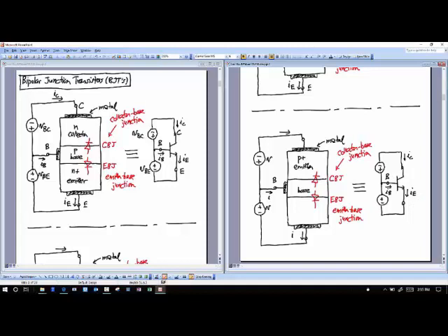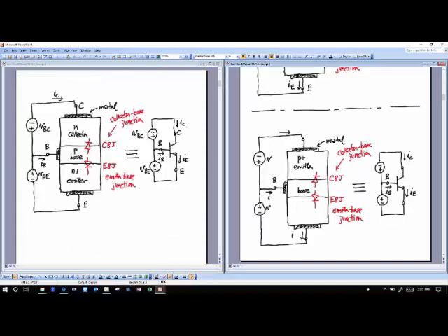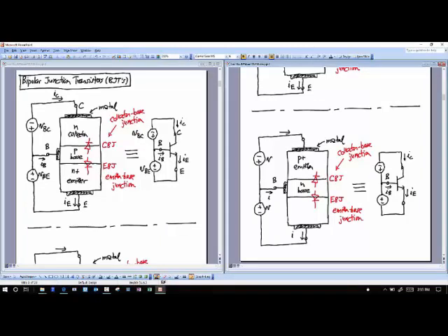Okay, so I've got a P plus emitter. I have an N-type base now, where it's PNP. And I have a P-type collector. Right, it's just the opposite of the NPN device. So let me even turn these diodes around. I'm basically making diodes in the opposite direction now. But it's still essentially a device that will operate in a similar fashion. Okay, those are my diodes, and I guess I even have to change my junction here. This is now emitter base.